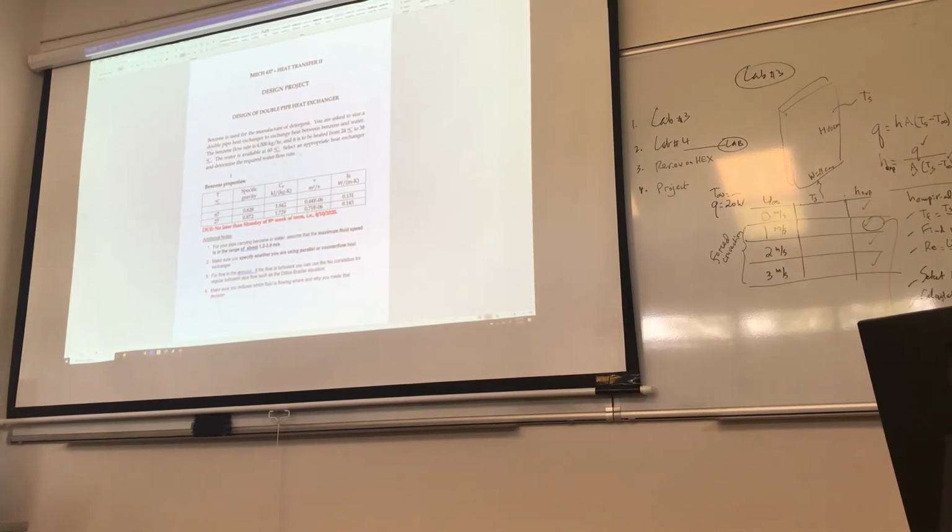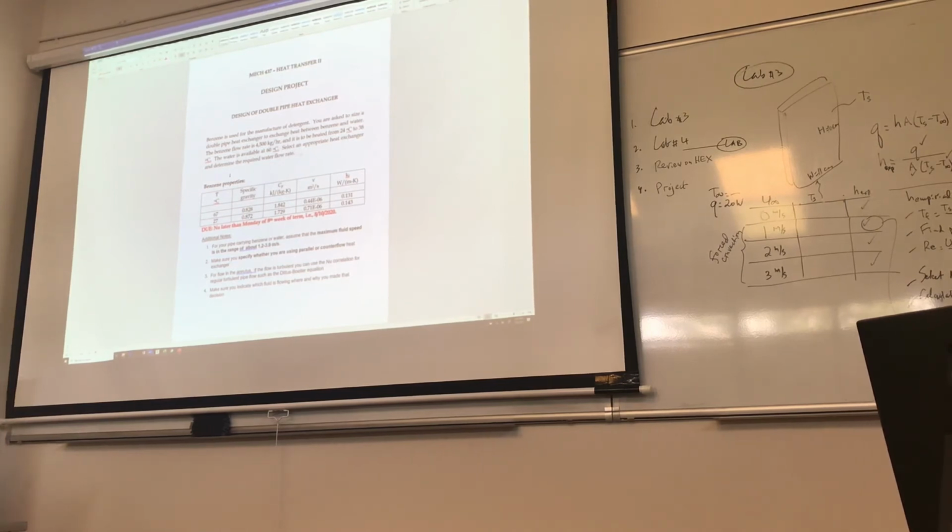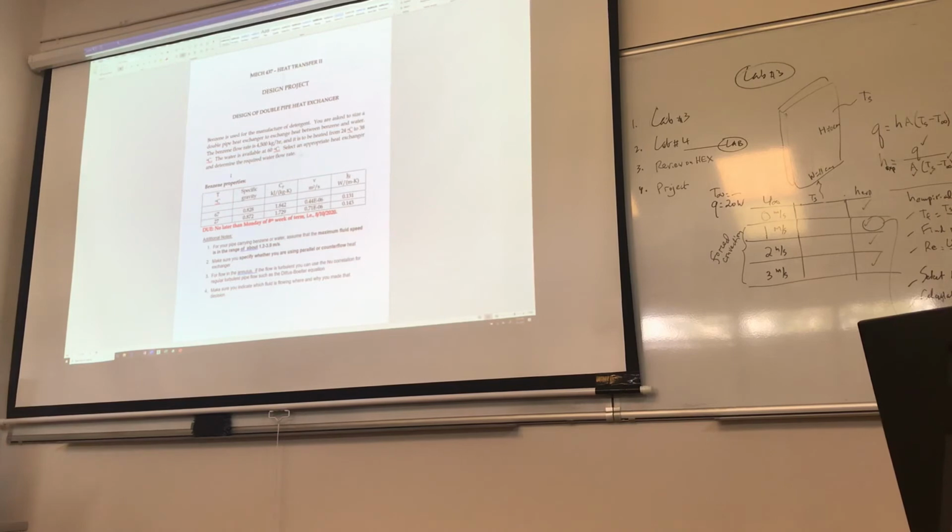That's the head loss, if you will, and the head loss is proportional to the velocity squared. So on one hand, you're creating high velocity, on the other hand, you're creating losses. To keep a fluid moving through a series of pipes like that, you need to make up for the loss in pressure. So that's another big headache.